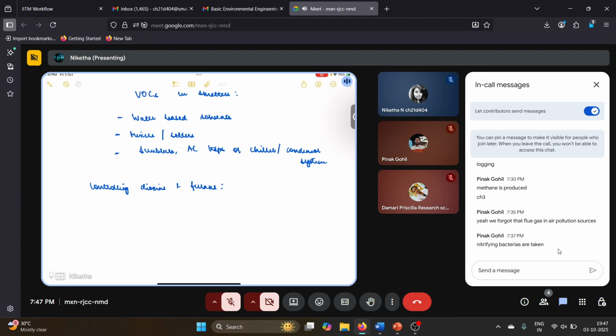So in order to avoid their production, we need to remove any organic compounds that are present. So this can be done by removing organics. And then we can use activated carbon in a fixed or a moving bed, so that whatever dioxins or furans are there, they can be absorbed. And how do we do noise control?